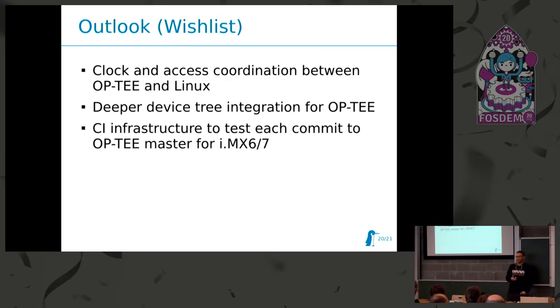So you need one OP-TEE binary, which is basically configured the same as the other one, but includes this write key provisioning. So it actually exchanges the key between the CPU and the eMMC for manufacturing use. So during manufacturing, you would write the key and then afterwards deploy your normal OP-TEE, which no longer does the key exchange, so the key doesn't leak.